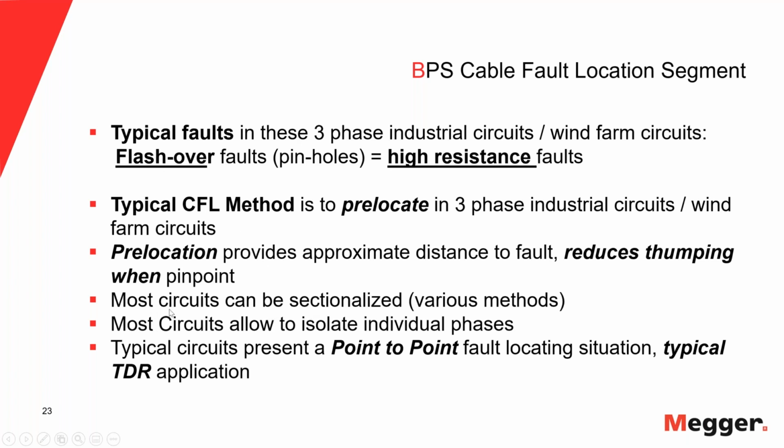Most circuits allow us to isolate individual phases. That's very important because you will see the difference when we talk about network systems, where that is not always the case. But in these circuits, we should be able to isolate individual phases, which again makes it a whole lot easier to fault locate. And so these circuits present really a point-to-point scenario. The TDR is a very good tool to apply to point-to-point fault locating scenarios, and that's what we have for the most part in these type circuits.